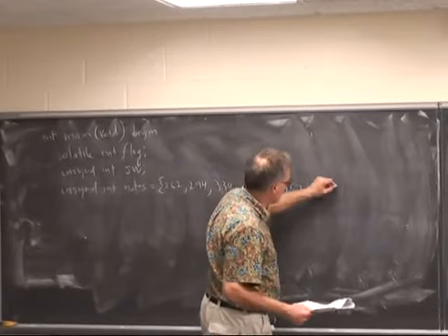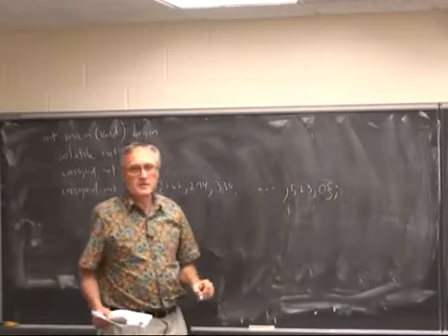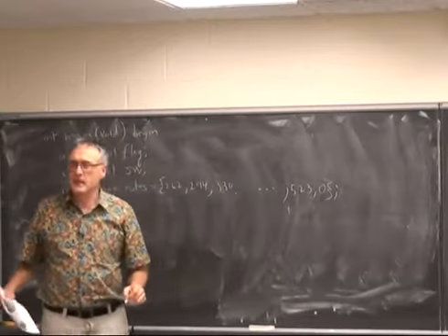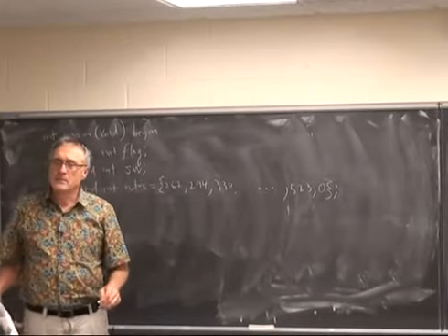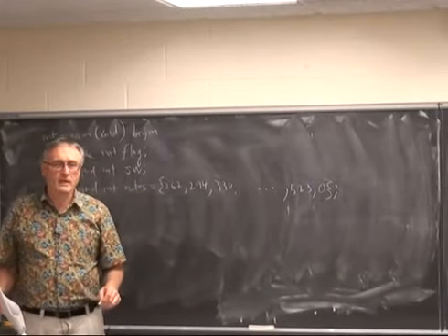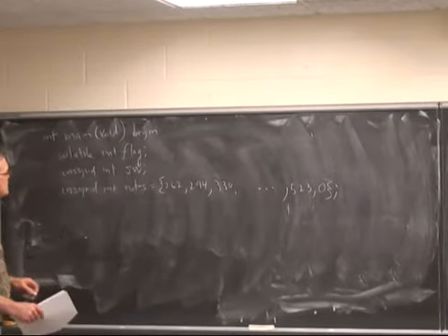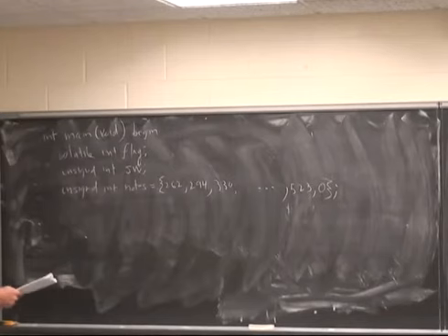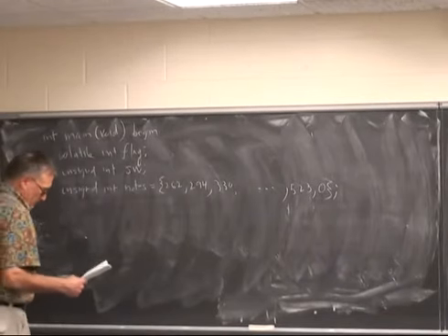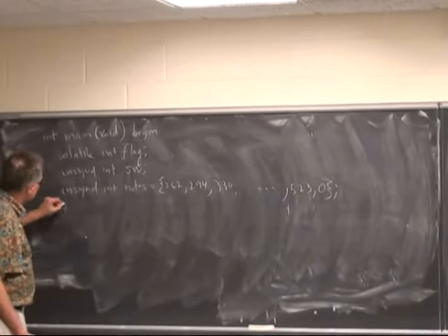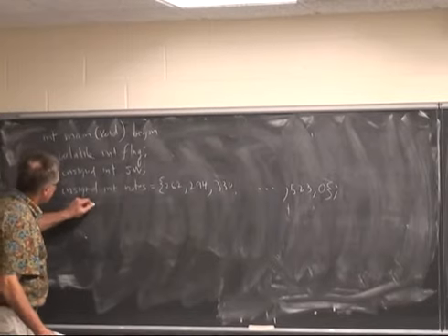And the 0 here causes the direct digital synthesis unit to increment 0 times a second, which means it produces DC, which you can't hear, so that's a rest. Set flag equal to 0.